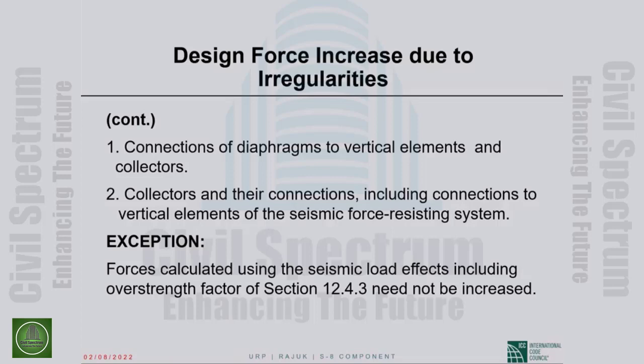Connections of diaphragms to vertical elements, meaning shear walls or frames, and to collectors. Those connections have to be designed for 25% more forces. And then collectors, the collectors themselves, and their connections, including connections to vertical elements of the seismic force resisting system, the collector to shear wall connection.